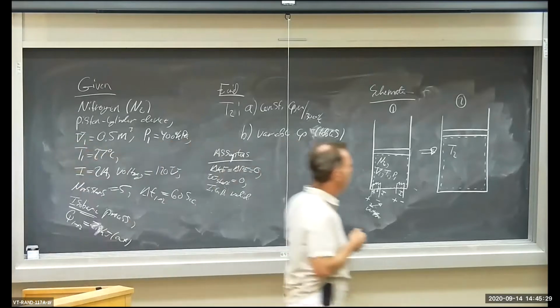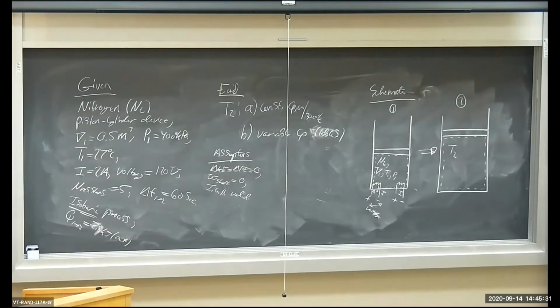All right, so let's begin the analysis here. Clearly, this is an energy balance problem. So to find T2, I need to find an internal energy at state 2. So I'm definitely going to have to apply the energy balance here. So let's apply the energy balance for an overall process. Q1 to 2 minus W1 to 2 is equal to delta E1 to 2.